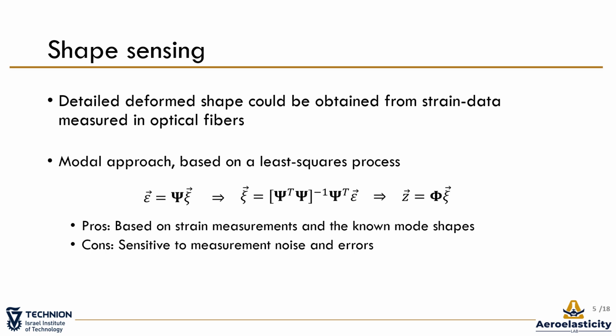Fiber optic strain sensors have seen in recent years widespread use in aerospace. The advantages are high sample rate, high accuracy, and easy installation, therefore a good fit for shape sensing. However, all measurements are subject to noise, which spoils the results. Plus, the system can experience process noise, such as turbulence or weight reduction.